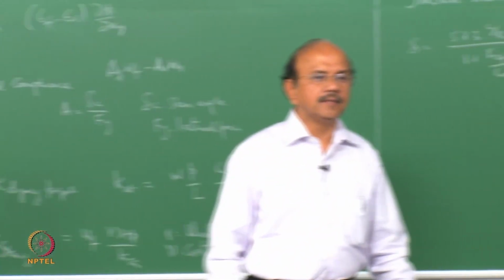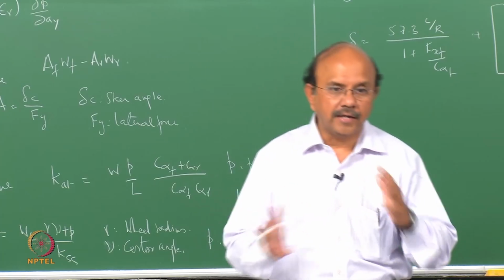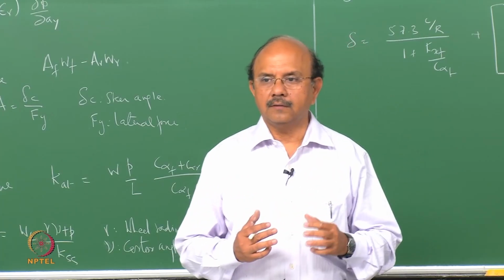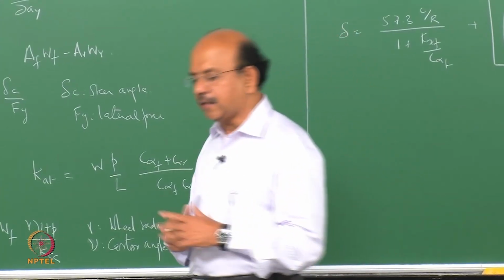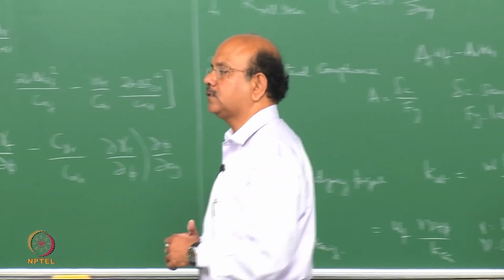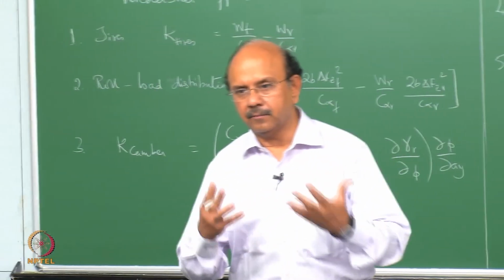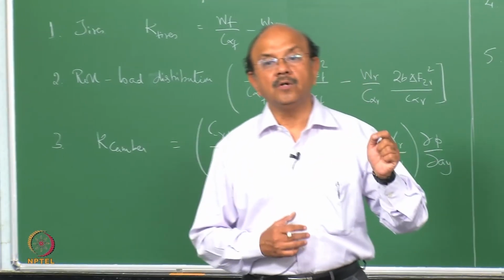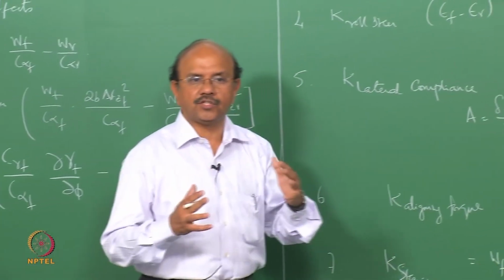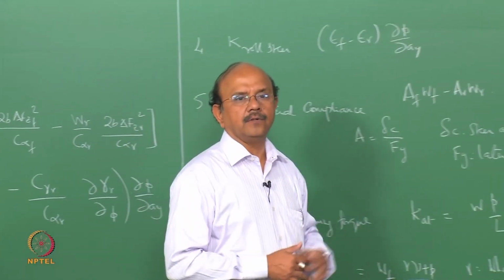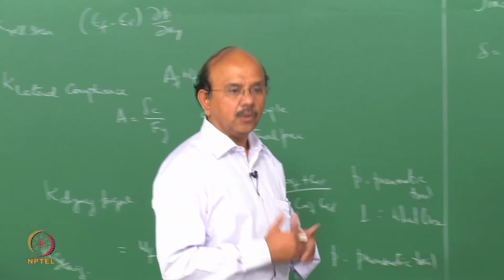We said that as there is a roll, there is a change in the angle of these tires, and that would again cause a behavior where I may have to give more steering input in order to compensate for that change of this tire angle, okay, and that's what we called roll steer.